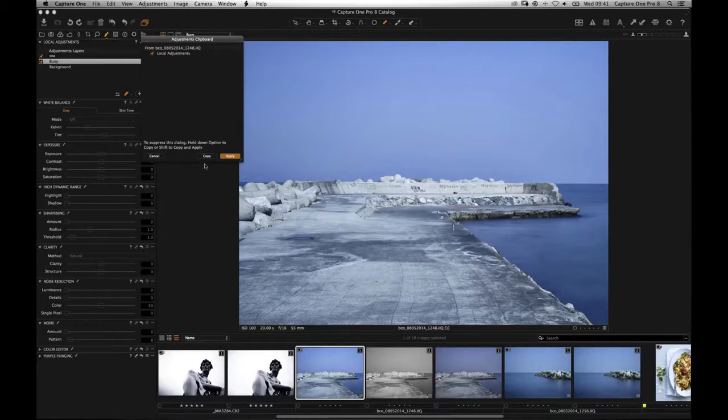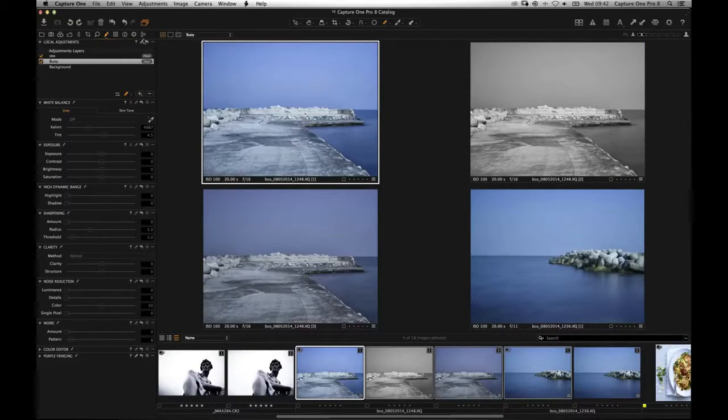If you want to avoid seeing this dialog and reduce the operation to one click, before you click here, if you hold your shift key down and click, it will simply apply it to all images. So if I select these 4 images, for example, hold my shift key down and click, then it's done. Then it applies that particular tool to all those images.